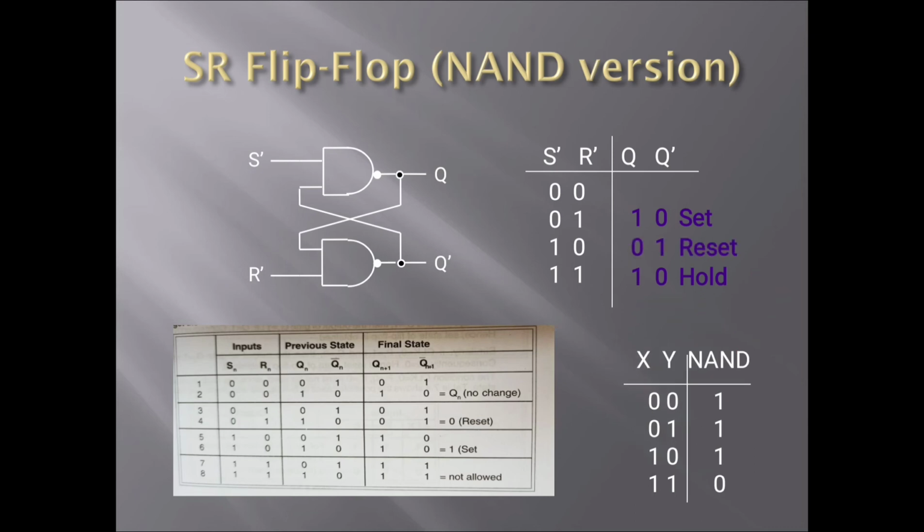Now in the next one, when we talk about the input as 1 0, 1 and 0, and in this case Q value is 0 and here Q complement is 1. Now this 1 is given to this and this 0 is given to this second NAND gate. 1 1 gives 0 and 0 0 gives 1, 0 and 1. Here is the 0 and 1.